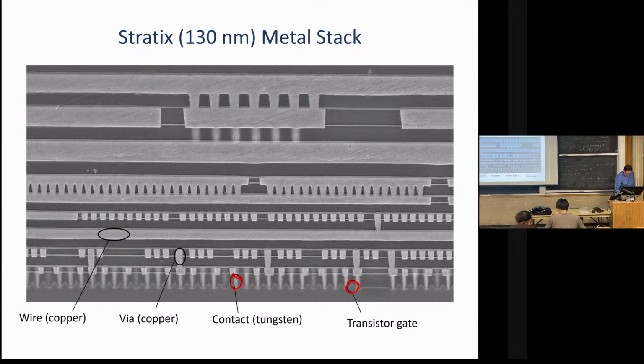And you can see the metal stack. The metal layers are going in orthogonal directions. So this metal layer, there are a bunch of wires that are coming out of the paper. And in this metal layer, the wires are parallel to the screen, so you just see kind of one wire. And then you see wires coming out again, and this keeps repeating. So what you can see is that these transistors are pretty small compared to the stack of vias that they're driving. And I've got little wires in the lower levels of the transistor stack.